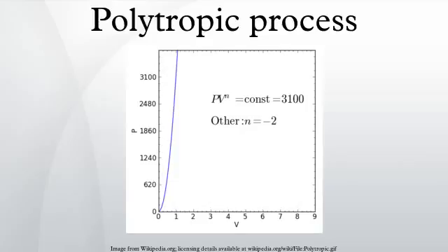Now consider the polytropic process equation itself. Taking the natural log of both sides gives the following, which can be differentiated and rearranged to give another form. By comparing this result to the result obtained from the first law, it is concluded that when the energy transfer ratio is constant for the process, the polytropic exponent is a constant and therefore the process is polytropic.